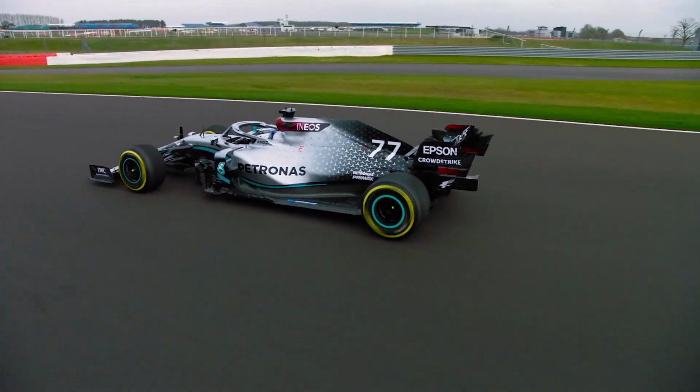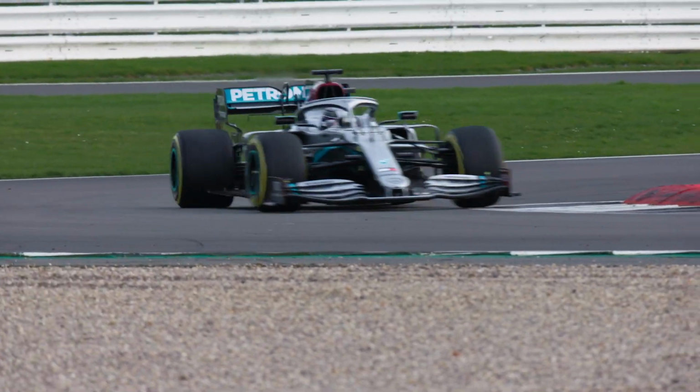The reasons that that's the case: below 10,500, through regulations, you can put less fuel in. There's a regulation that allows fuel flow to go up linearly and then flatten out, and it flattens out at 10.5. Below that, it's influenced by that. Above that, you start getting influenced by friction. Friction, the amount of force and rubbing that you lose through bearings, goes up with speed and some parts speed squared, so all of a sudden the friction is getting much, much higher. That means that after that, you start to dip off and roll off the power. So it's that shape of the power curve that's being matched by the shift point.